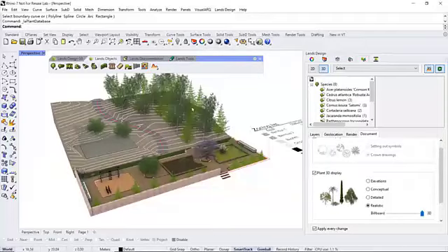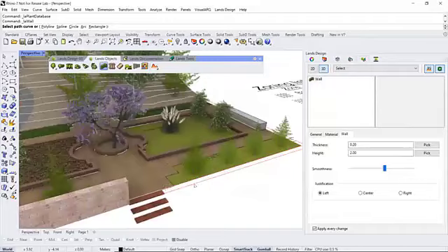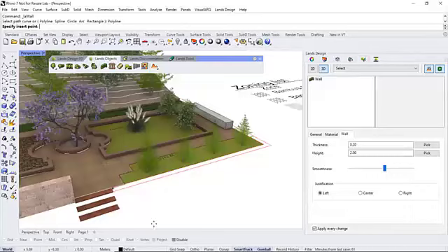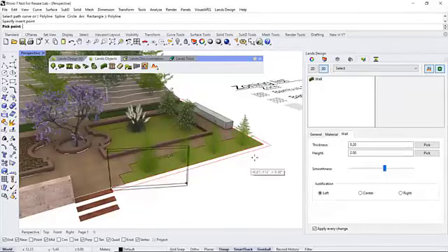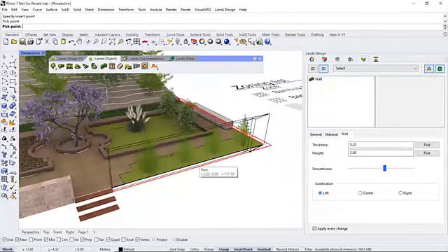Okay, let's go on with some of these civil work elements. For example, we can see how to insert a wall. Basically, a wall is a parametric object defined by a thickness, a height, and some alignment and justification. Now we can draw, for example, a wall following this contour using this polyline option in the command. Enable the osnaps. I've got the justification to left, so I'm just going to osnap that corner.